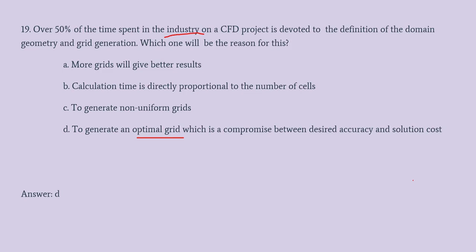So my question is, why do we need this geometry to be reduced into more number of cells? Why are we going for a maximum number of points? Because the element length, that is the distance between two nodes or vertices of our geometry, as it is being decreased, that means our derivative is better approximated.